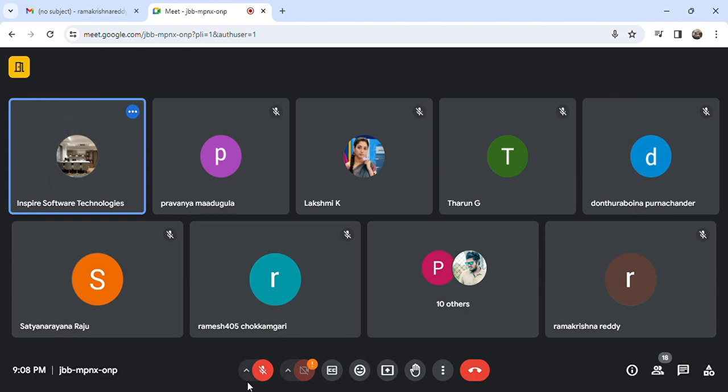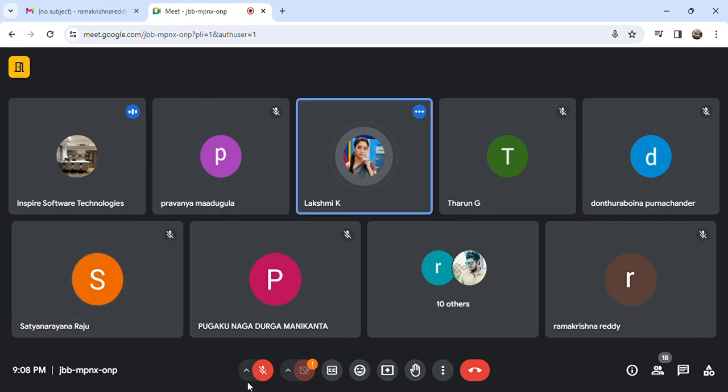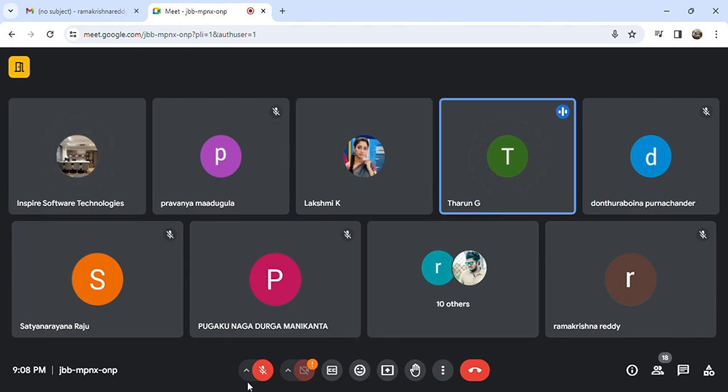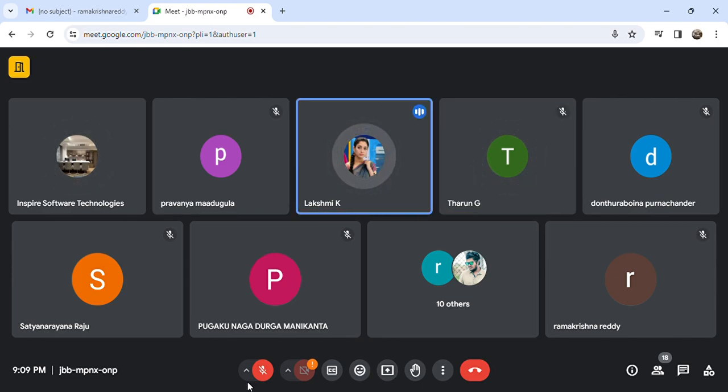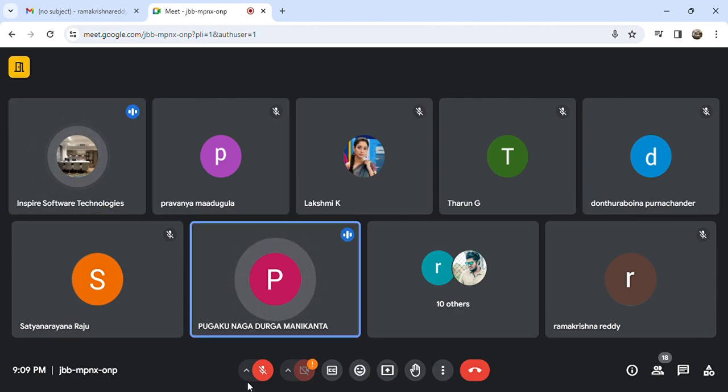Okay, and what kind of errors are possible in CAN? Bit error, stuff error, form error, acknowledgement error, CRC error. And active error and passive error. You should not tell active and passive as types of errors. When you are explaining the error frame, then you can mention active error frame and passive error frame.